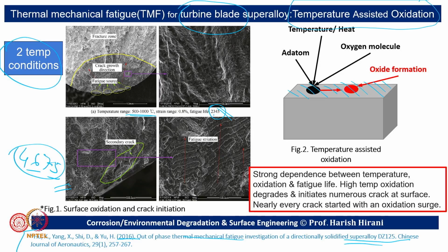So what is really the difference? They are still able to find some sort of ductile failure. They can see secondary cracks and striations, which have been shown here as fatigue striations. But in this other case, they find more ridges, and there is a greater possibility of fracture. This portion has been zoomed in this manner, while this other portion has been zoomed in that manner.